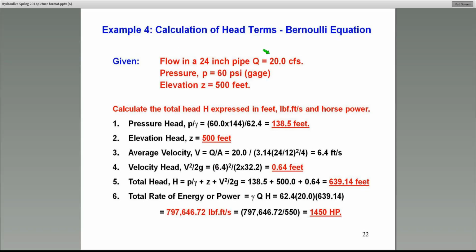The pressure at a point is 60 psi. Typically, that's how we measure pressure. It's also what we call a gauge pressure, that is related to the atmospheric pressure. We do not use absolute pressures in fluid mechanics. Gauge pressure is basically the relative pressure relative to the atmospheric pressure, so it's absolute minus the atmospheric. So anyway, 60 psi is the pressure above the atmospheric pressure. It's positive. It's pounds per square inch.